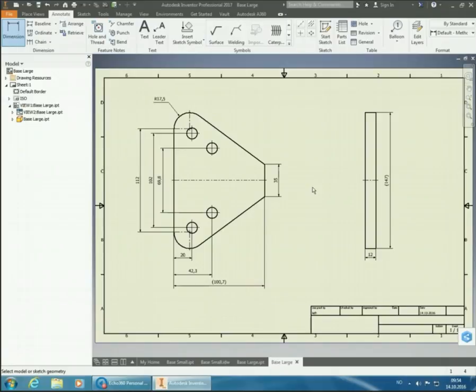And now we just need to put in the hole dimensions. Since we created 4 points, and then we used the hole dimension, and it created all 4 holes in one go, we won't have to edit the quantity note and tell Inventor to count all of the like holes in the same view, because it's just going to count all of the holes it created with that one hole function, because it created 4 at once.